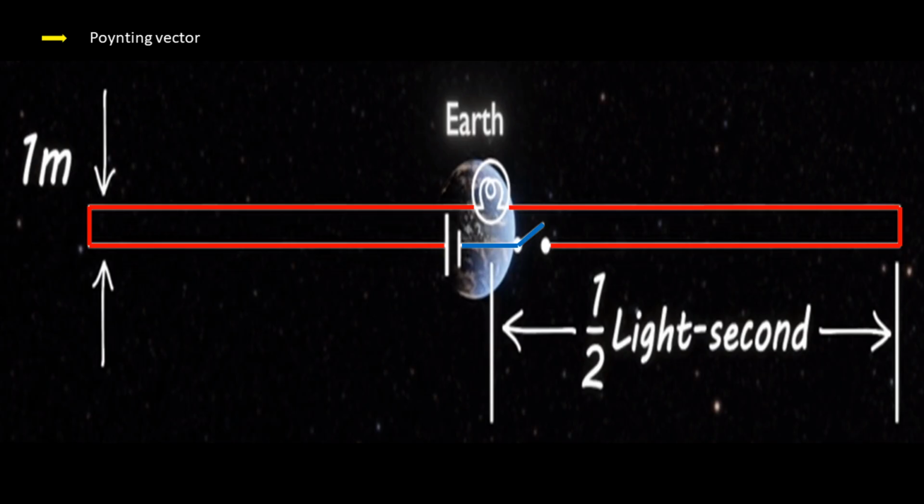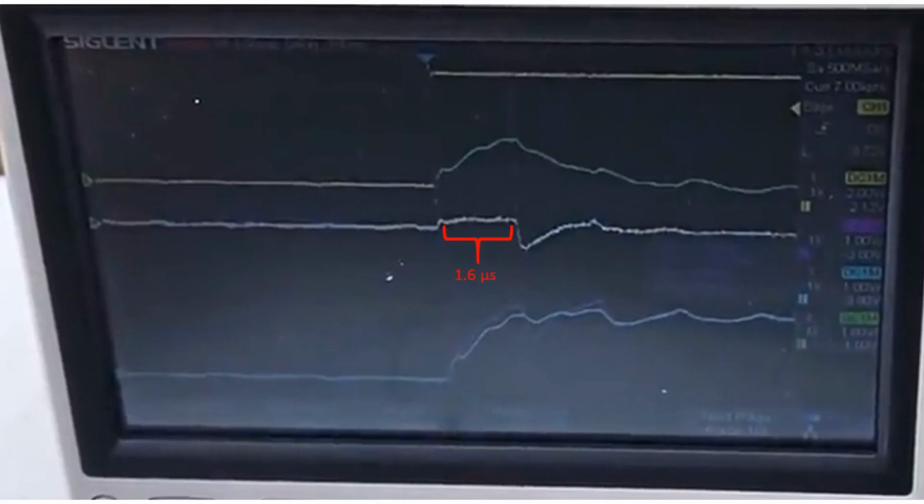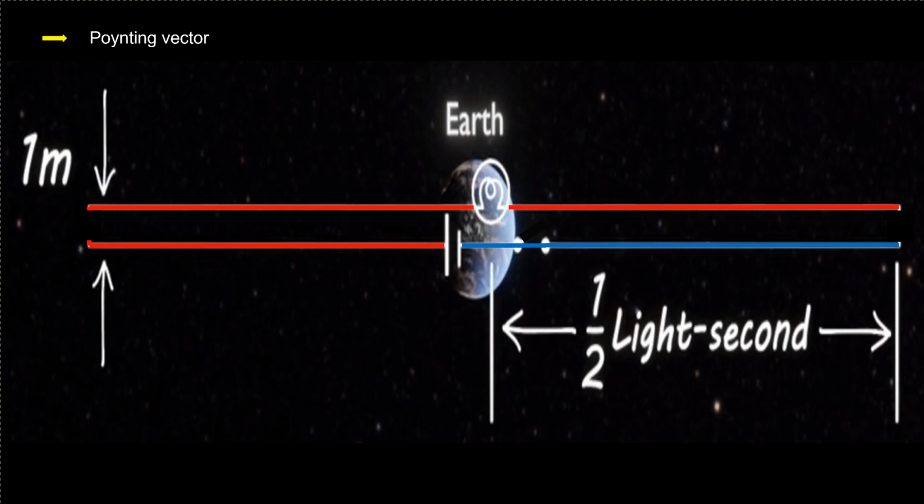This can be further demonstrated by looking at a situation where conduction is impossible. For example, let's take our circuit and cut the wires at each end. Now, it may appear that no energy can reach the light bulb from the battery, but if we were to flip the switch, we would observe the same capacitive coupling effect, meaning the light bulb would receive the same amount of power for the first second. In fact, Alpha Phoenix ran this test with his small setup and saw the same 0.2 milliamp jump for the first 1.6 microseconds. So even though there is no steady-state Poynting vector for this setup, we still see the Poynting vector during the transient period, showing that one does not necessarily correlate with the other.